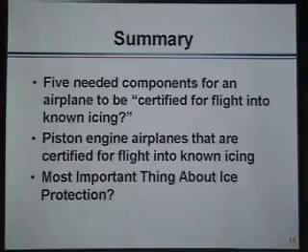Now, let's say you're flying that 1955 Beechcraft Baron from Flagstaff to Albuquerque, New Mexico, flying bank checks. If that airplane has these 5 things on it, you've got pneumatic boots, alcohol props, alcohol windshield, dual pitot-static systems, and they're all heated. If you get into icing conditions, you're probably going to need to advance the power lever to full throttle, and you're going to operate all of your ice protection systems.